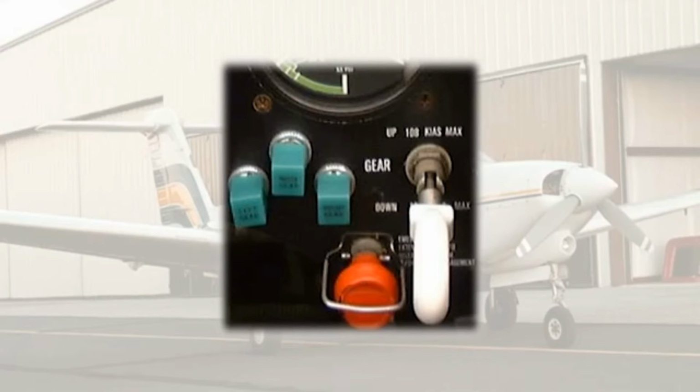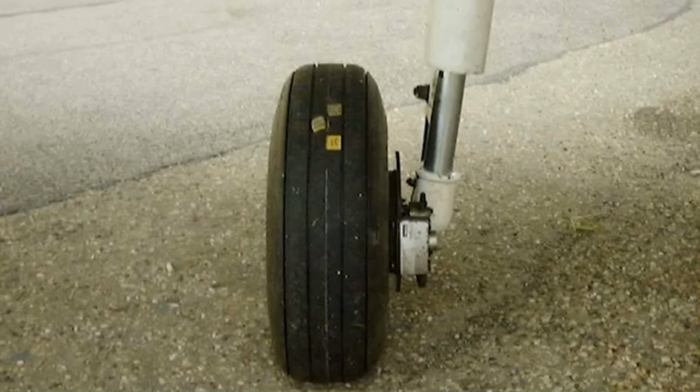Undercarriage wells are normally sealed by doors for aerodynamic reasons. Aircraft wheels are fitted with pneumatic tyres. These can consist of both a rubber inner tube and an outer cover. The tube contains compressed air which absorbs shock and supports the weight of the aircraft, while the cover restrains and protects the tube from damage, maintains the shape of the tyre, transmits braking effort, and provides a wearing surface.